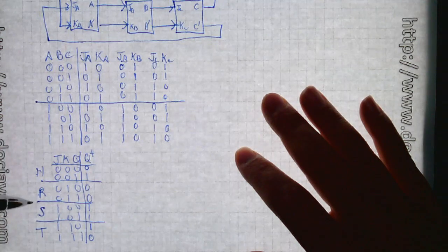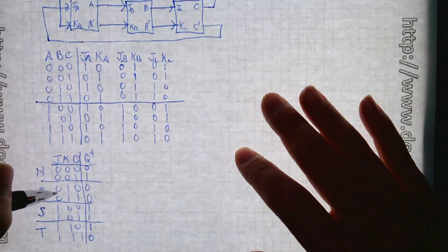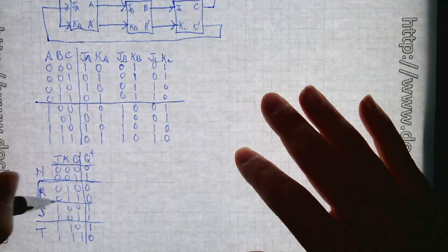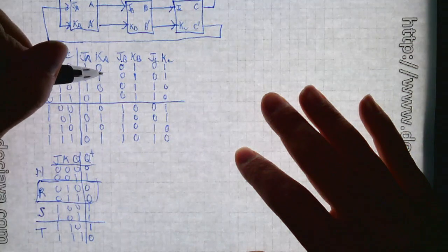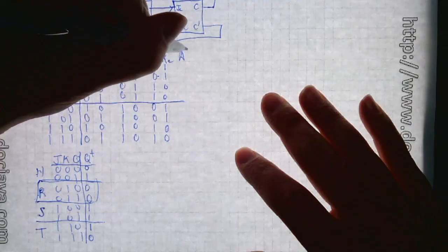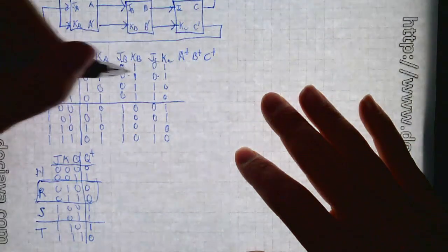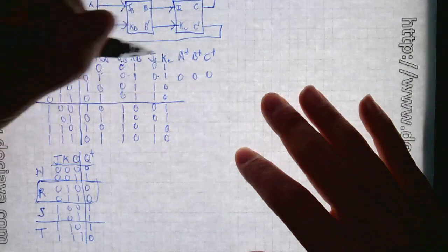But we're not seeing that here, not with this counter, right? So this counter basically says, look, 0, 1 is being used. So if I see 0, 1, which is here, here, and here, then the outputs A plus, B plus, and C plus must be all 0. Any place I see 0, 1, it must be 0.